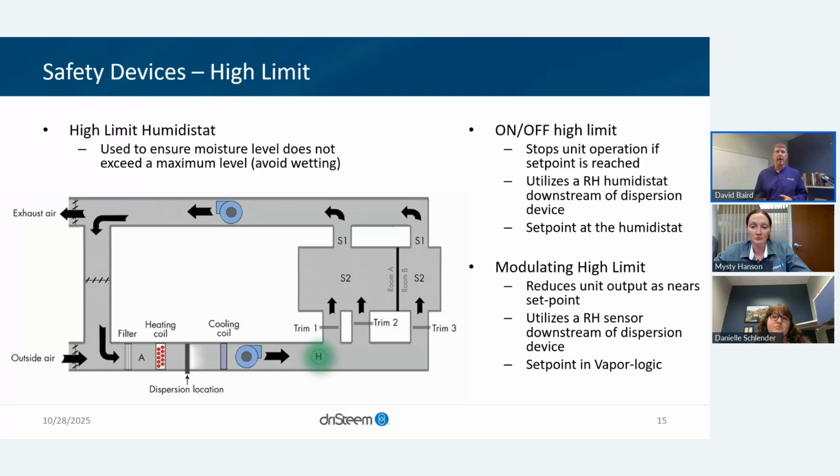You want to give it time to mix. Granted, if you've got a lot more contact points between the steam and the air, it'll mix faster. Space them further apart, it's going to take longer. You want to give it time to get a good reading.